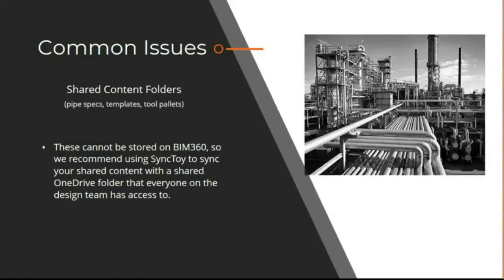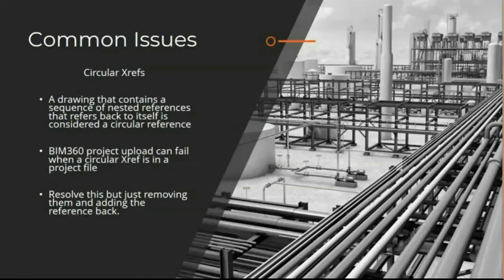So go on to the next one, circular Xrefs. We had a particular customer that we could not figure out what was going wrong with uploading his projects. He would start uploading his projects, and he would get about 95% of the way through, and it would just stop, and we could not for the life of us figure it out. So we finally dug in. We found out that there were circular Xrefs.